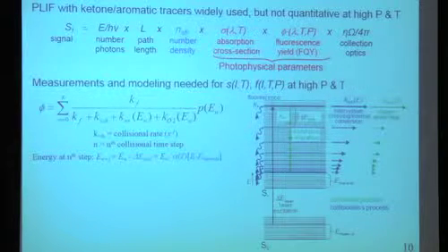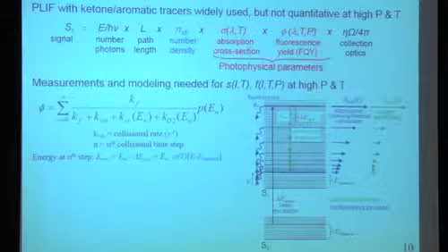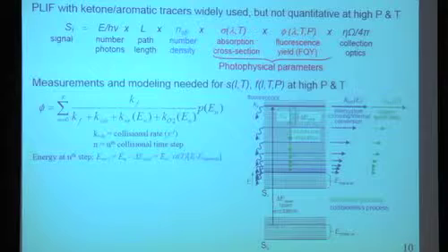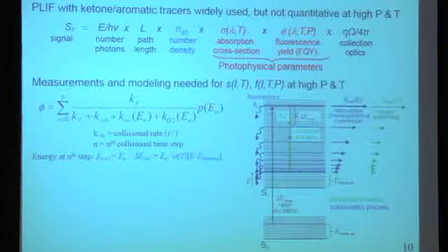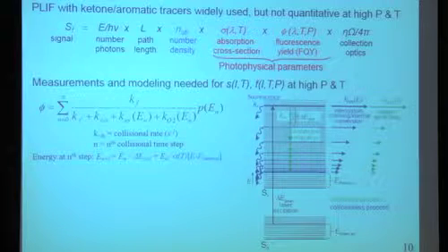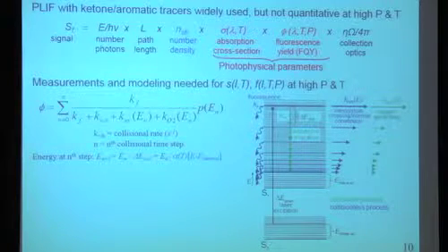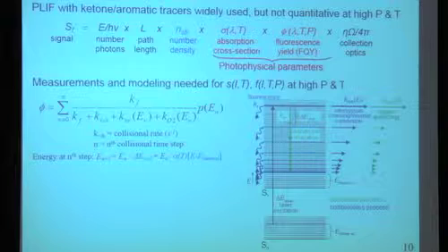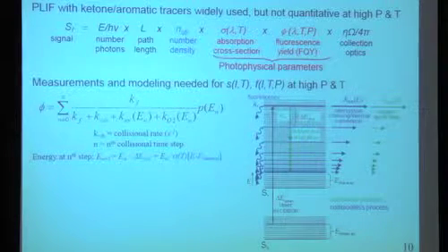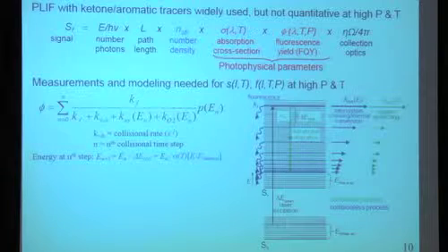And it turned out it was because they were using different wavelengths of illumination, and that we hadn't yet realized that you have to think about temperature not because of the quenching directly, but because of the number density. So anyway, over time, everybody uses acetone, and it's very simple if it's isothermal and isobaric, but if I wanted to do this in a compressible flow field, if the temperature is varying and the pressure is varying, you have to think a little bit more.